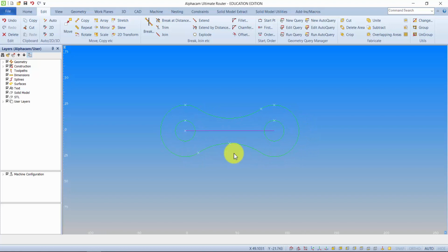The first thing that you should do is press Ctrl G and you'll see there are too many ghost tools. Now I've mentioned ghost tools a lot and they'll be more important today. Ghost tools show, if I press Ctrl G again, where the cutter will engage the workpiece and the direction it will travel. But obviously this outer profile does not require the 5 or 6 ghost tools that are there. I just need a single ghost tool. That's why we join, all, and finish. And that's more like it.